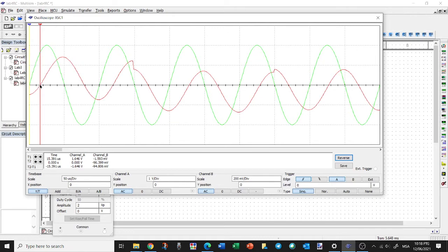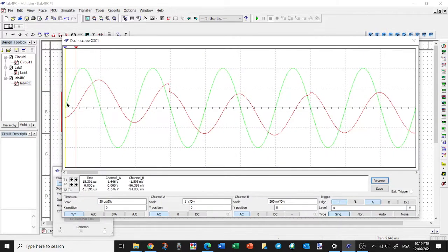Okay, so go back and see, for example, Ismail dia punya phase shift dia ialah minus 15.39 microsecond. So you convert that microsecond into degree angle darjah, which is I think angle equals to frequency multiplied by dia punya time multiplied by 360. I think so lah. You go and check again. Alright, so this is how you measure the phase shift.